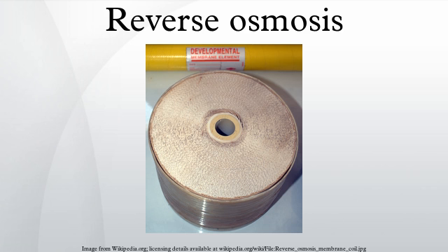Each branch of the United States Armed Forces has their own series of reverse osmosis water purification unit models, but they are all similar. The water is pumped from its raw source into the reverse osmosis water purification unit module, where it is treated with a polymer to initiate coagulation. Next, it is run through a multimedia filter where it undergoes ion exchange. It is then pumped through a cartridge filter which is usually spiral wound cotton. This process clarifies the water of any particles larger than 5 micrometers and eliminates almost all turbidity.